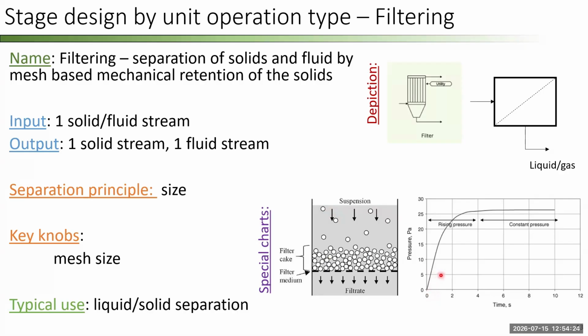In general, we have two regions as I turn this filtering process on. Initially, it doesn't take very much pressure to push the liquid through, but over the course of the first 4 seconds, we have a rise in the pressure needed to push that suspension, that combination of liquids and solids, through the filter.